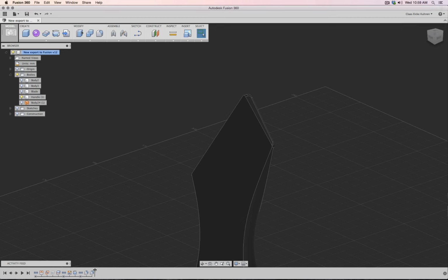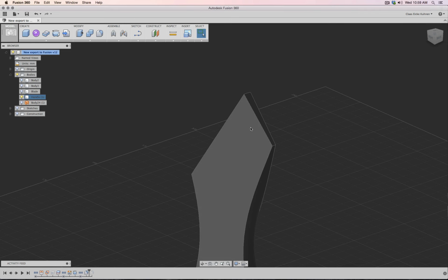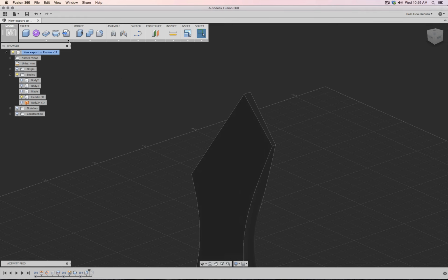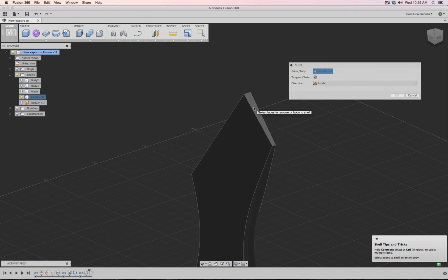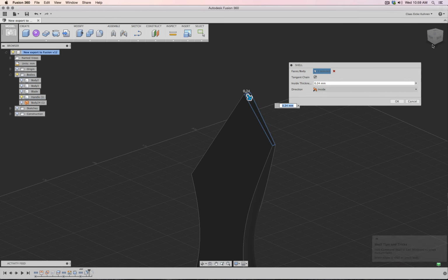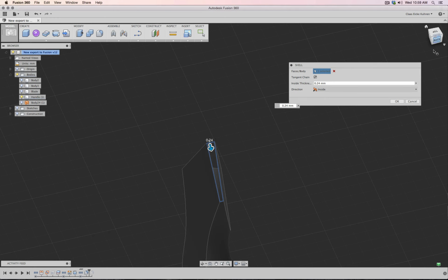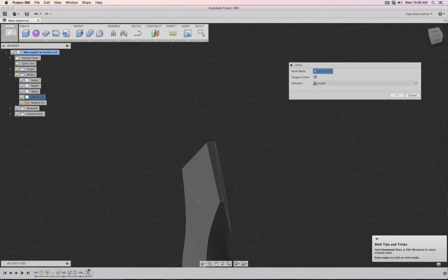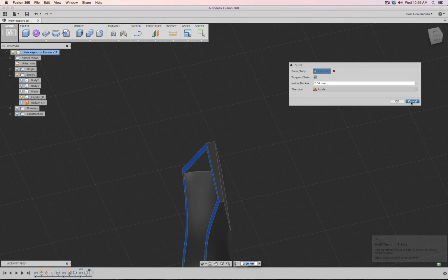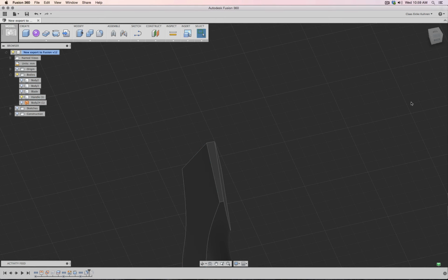Now we would like to shell it, and I don't want to shell this and then actually have those edge roundings being offset as well. So I go back to this sharp one, and then actually here maybe I could go to shell and say shell me out this part. And no, hold on, shell this one. Oh, annoying. That's not really good. That's pretty silly.